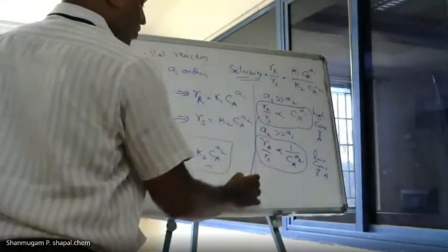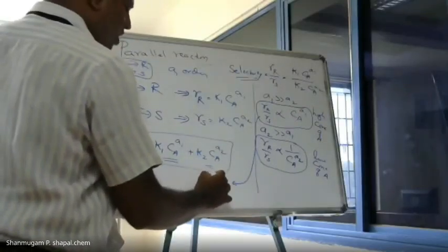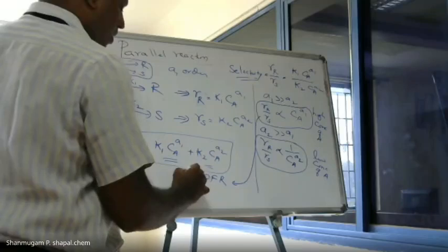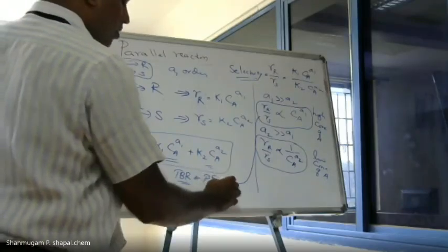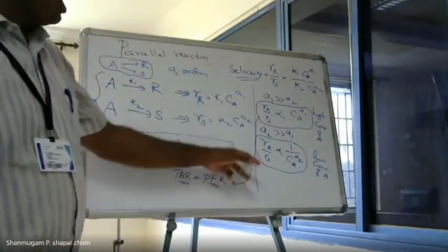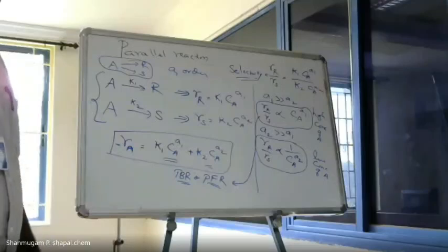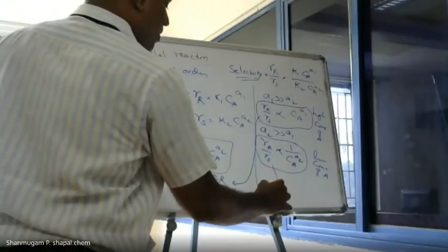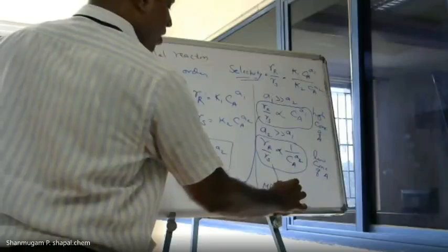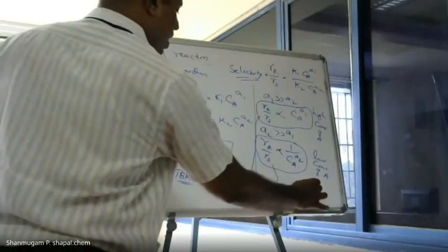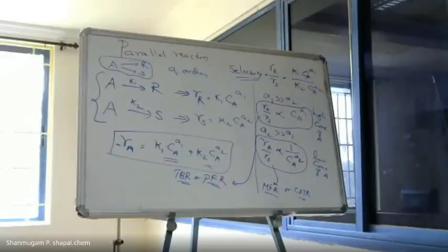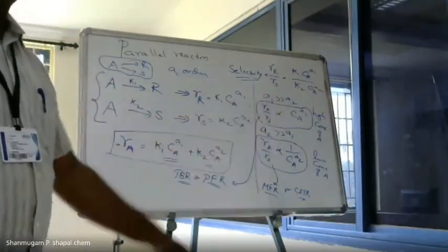So we always prefer for the high concentration a PFR or a tubular reactor. The tubular reactor or the PFR would be preferred for the high concentration reaction mechanism. If you go with the lower concentration, it is preferred to have the MFR or CSTR in practice. This is the dependence of the concentration with respect to the rate.